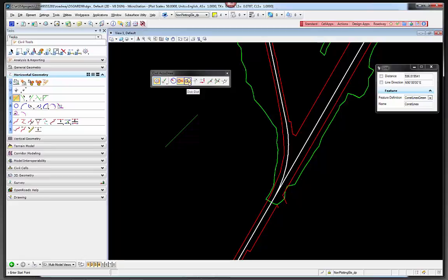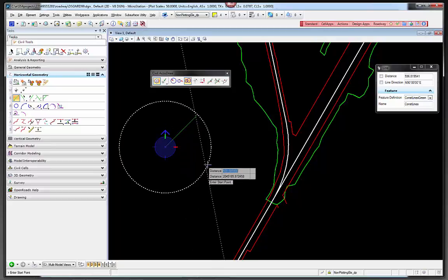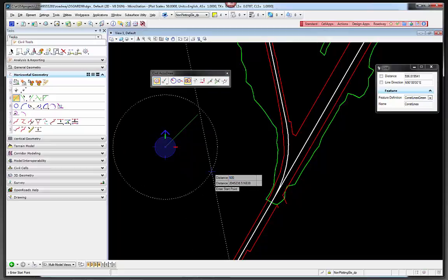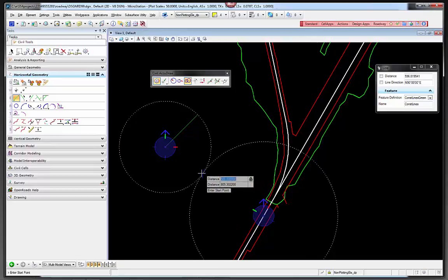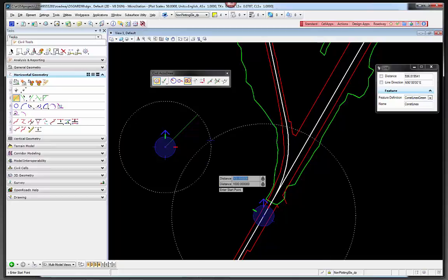Now here's one with distance. So let's say I want to start the first reference off of here, so I select a reference point off of this point here, and I could set this value to 500. And then for my second distance, I'll select another offset point here, and then it automatically finds where they're common, but let's say I set that to 1,000. Oops, 500 for that one. You just have to make sure that the focus is in the right field in order to lock it in. And in order to lock it, I'm just hitting the Enter key, and you get the lock button.